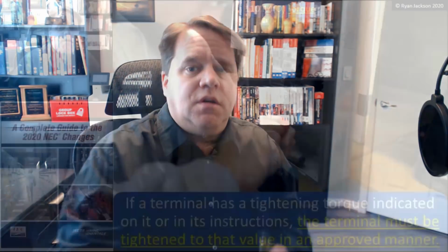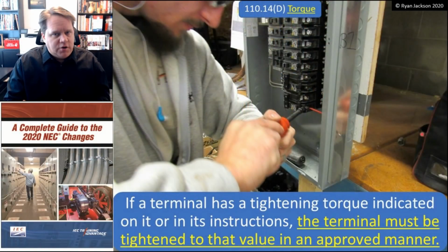And as I stated at the beginning of this video, terminations are one of the most important concepts of the entire installation. We need to make sure we're doing them right. So her research really brought this issue to the forefront. And when her work was published, and by the way, it's available online, you can find it, if I'm not mistaken, it's in an IAEI article, International Association of Electrical Inspectors. But research her work, and I think you'll find it fascinating. I certainly did. But it really made people aware of the fact that people are not doing this right. So we need to make sure that we're measuring torque.